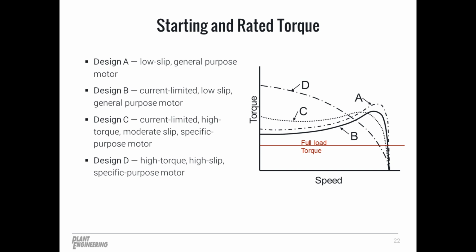with the current limitation. And then NEMA Design D would be just like Design C, but without that starting current limitation. NEMA Design A and B motors would be popular for typically centrifugal applications like blowers, fans, pumps, general industry, process use. And then NEMA Design C and D motors would be better suited for high starting torque applications like elevator, crusher, conveyor, air compressor.